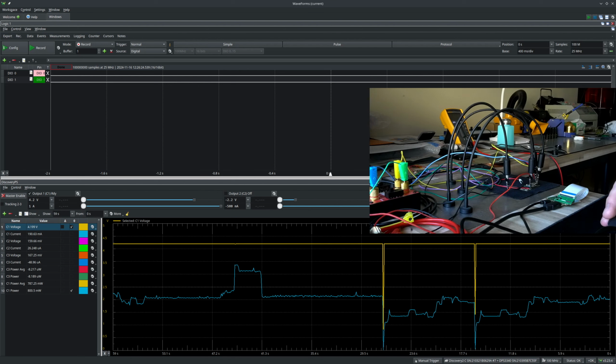So specifically, I'm talking about these low power mode commands, the low power data transmission that happens often before you set the link into high speed mode and are sending video data on all 4 of the DSI lanes. So in this particular setup, I've connected both the P and N, positive and negative sides of the differential pair of data lane 0, which is where this low power data transmission is going to happen, to a logic analyzer, in this case the Analog Discovery 2, and I have WaveForms here.